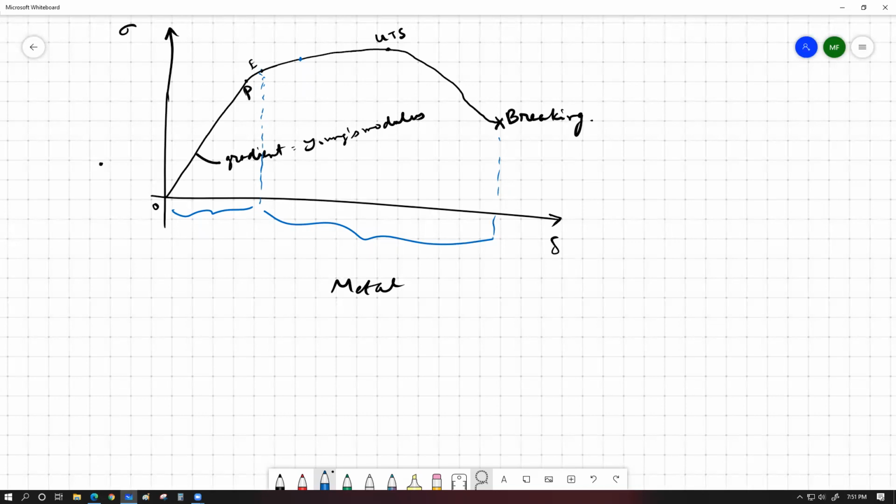And how much deformation would be left? That can be found out by drawing a parallel line, which is parallel with its OP section over here. So this line, if I'm drawing somewhat, this is parallel to this part, then the object is going to come back to this much shape, and this is the part that is going to remain within the object that we define as permanent deformation. Sir, parallel, sir, how far can it go? I mean, what's the distance to which you have to hold parallel, sir?